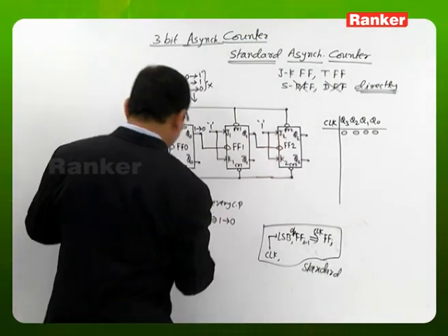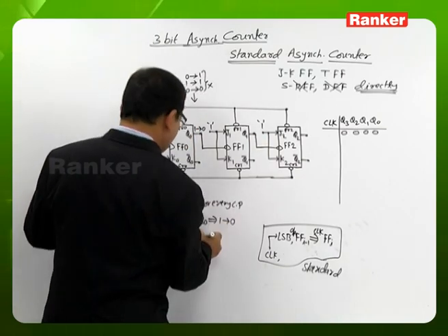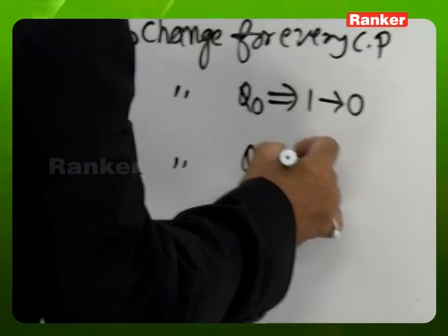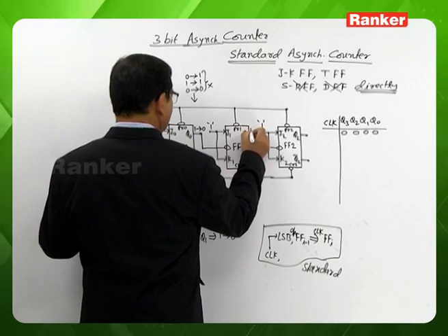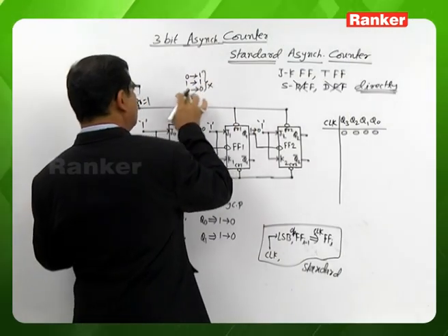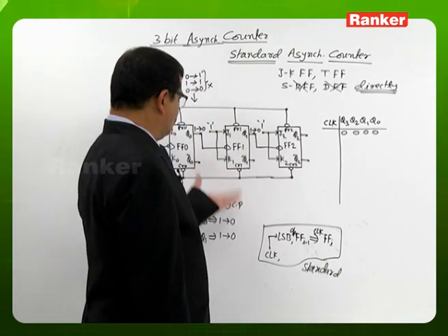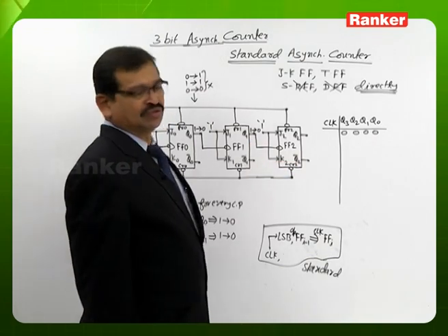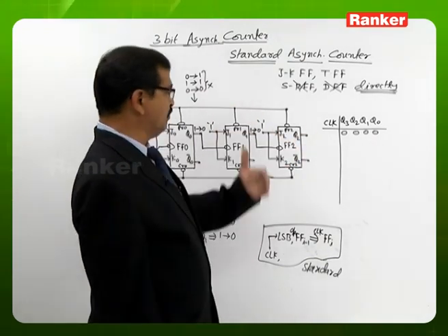Similarly, if you look at the flip-flop 2 output, that is Q2, Q2 is getting a chance to change its value if and only if Q1 is changing from 1 to 0. In other words, whenever Q1 is changing 0 to 1, or 1 to 1 or 0 to 0, that is not giving a clock effect on flip-flop 2. So knowing this, it becomes easy for us to work out the operation of the circuit while applying the clock signal.